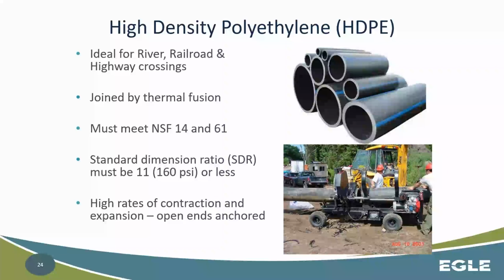So basically what that means, and I'll dive into a little bit of an example of that, is thermal fusion is you're heating two ends of two sticks, and that's what you can see in the bottom right corner here in that picture. Then you're basically going to be forcing them together until, for all intents and purposes, they stick together and they have a pretty strong bond. You're actually pushing those materials so they're now connected, right? So those have their own NSF standards, 14 and 61 as well, same as the PVC.